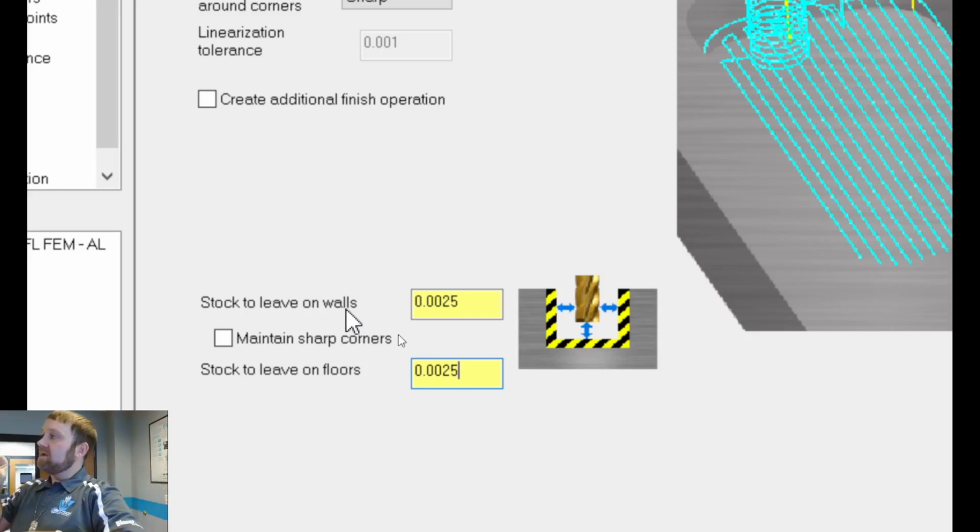If you don't cut the pocket deep enough, then the part's sticking up higher than it should. If you deck it off and measure it at 1/4 inch, then take it out and measure it, it's probably going to be undersized. Or if you cut the pocket way too deep, you're going to face it off and probably freak out when you measure it and it's 200 thou sticking out, because you cut your pocket 50 thou too deep. So this stuff all correlates. It's what's locating the part.